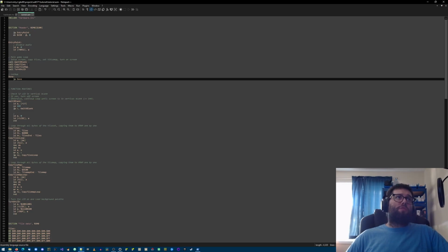Then we're going to make a call to a routine that copies all of our tile set into the video RAM. Then we're going to make a call to a routine that copies our data for the tile map, to tell us where to put all of those tiles and in what order to make it show that mountain image. And then lastly, we make a call back to the LCD controller to turn the LCD back on. Then we just do an infinite loop where we keep jumping back to this label called done, so our image will just keep staying up on the screen and it won't go away until we close our emulator, or if this was on a real Game Boy, until we flipped the power switch.